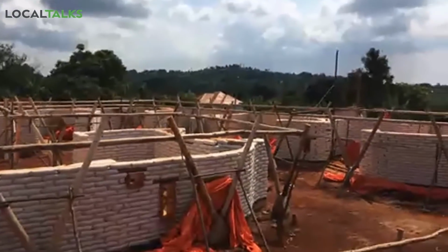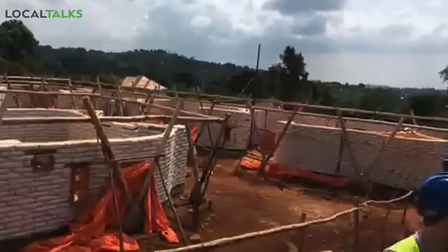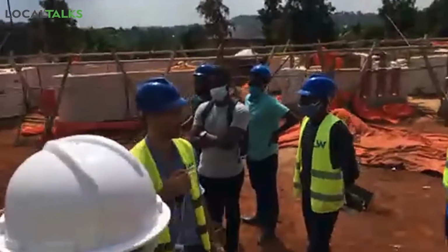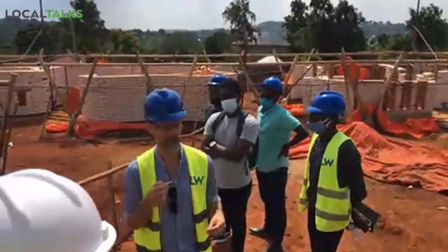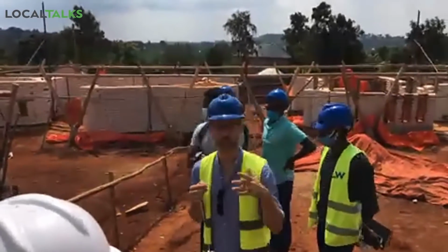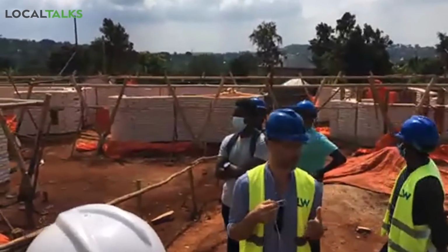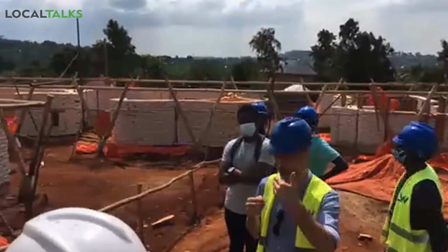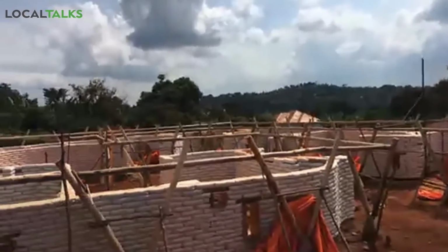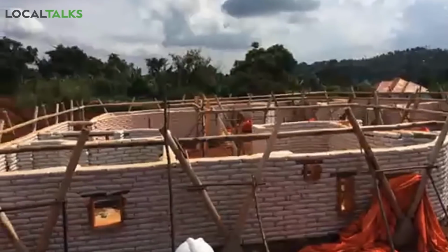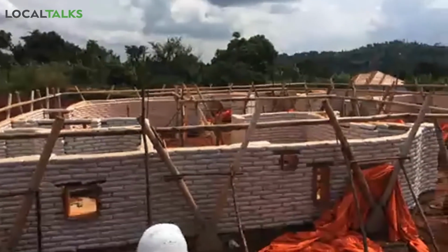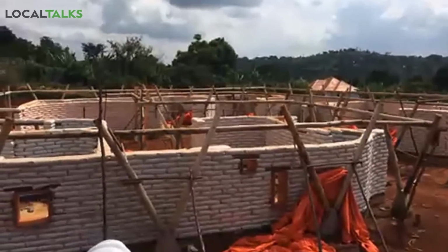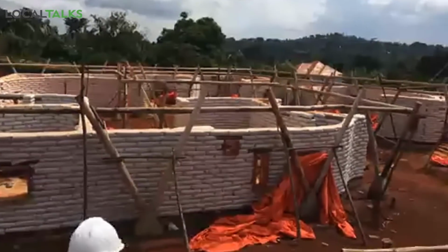That is actually a timber frame that will be clad with the same material that we use for all the ceilings, which is a woven mud. And that timber frame that goes all the way up is doing the bracing of the building and connects the roof to the structure. So our entire earthbag construction is finished. We are no longer building any earthbags. We are done. That is the final height.